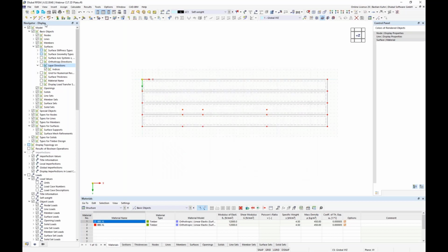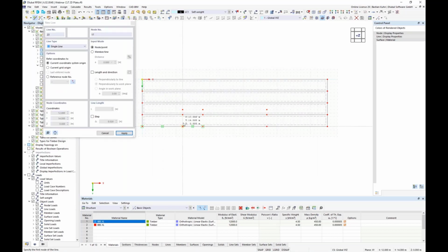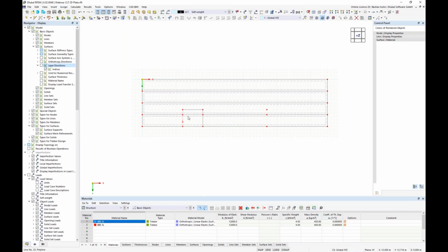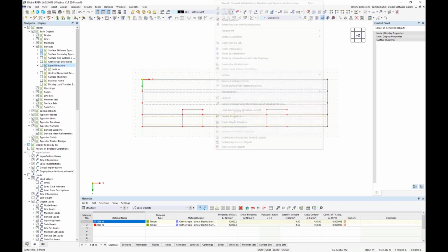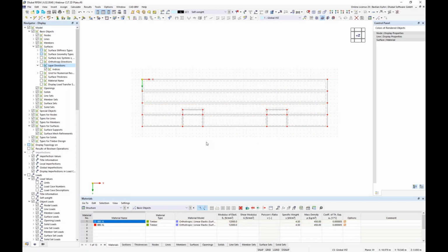Say okay, and then I have it there, and then I will draw a few lines in here and there. And this one I will be copying via drag and drop onto the right side. Okay, I will connect the lines in here, and then it's okay. And then a very nice function, not a feature, is if you right click in here, you can divide the surfaces by integrating lines. And now you can just delete the surfaces which we do not need.